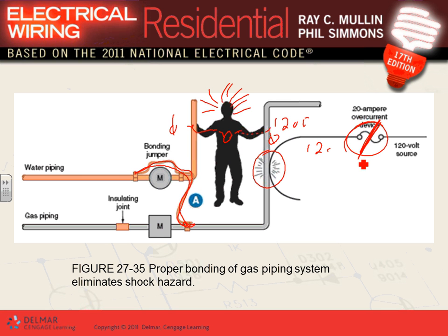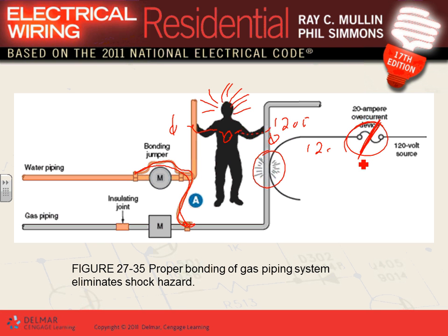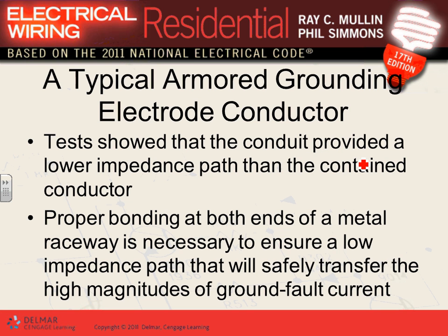And think of any place in this building or in a house that does not have a 120 somewhere. For 50 years, the people are going to be behaving in these rooms. That's our job, to protect the people by bonding these equipments. Gas lines and so forth, and that could be anything. See the grid here, right? The grid above your head. Could this grid be energized? Yes. So what do they do with the grid? They bond it. That grid will be bonded to the equipment grounding conductor. So if that grid is to become energized, the circuit breaker will trip.